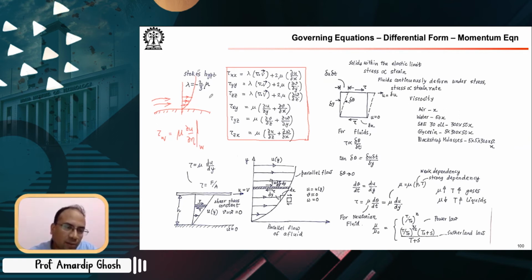The V component is not zero inside the boundary layer, but it's really negligible. The W component is there, but if you are talking about a 2D problem, flow over a wing where you take the cross section, we often ignore it. Of course, it depends on the problem and on the way you align your coordinate system as well. But long story short, in this case we are looking at a parallel flow problem. Your streamlines are oriented parallel to the surface, and the gradient of velocity is primarily in the wall normal direction.